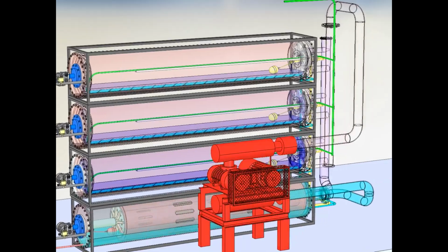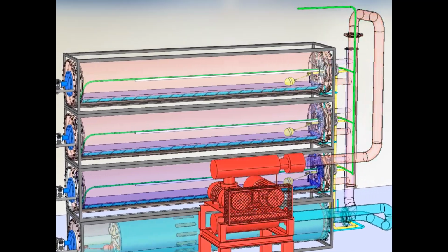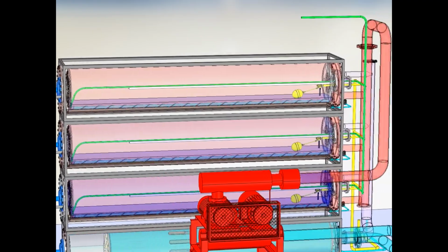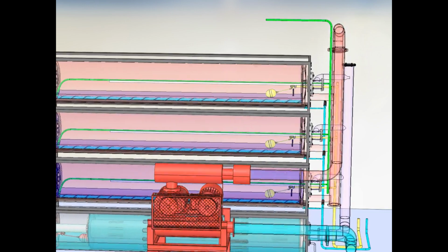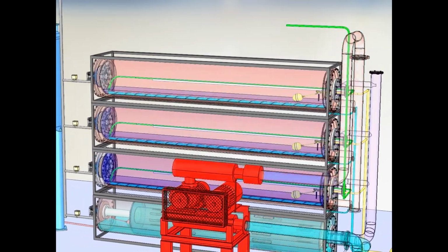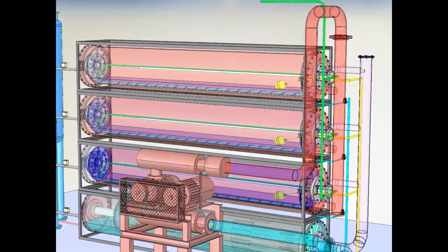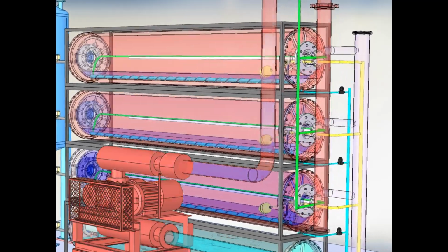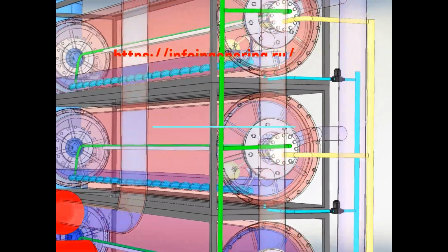In the absence of high-pressure steam, the optimal technology is mechanical steam recompression, when film evaporation drum modules are connected in parallel. In this case, the steam generated in the modules is sent through a manifold to a compressor, for example a Roots pump, and after increasing the pressure and temperature of the steam in the compressor, the same steam is sent as heating steam from the same film evaporation drum modules, where it condenses on the outer surface of the rotating drums. With this scheme, there is no need for a source of heating steam and a cooling circuit for its condensation. This technology can be used to concentrate liquid radioactive waste for subsequent immobilization, for example, in a cement matrix. More detailed information about this can be obtained from the links.